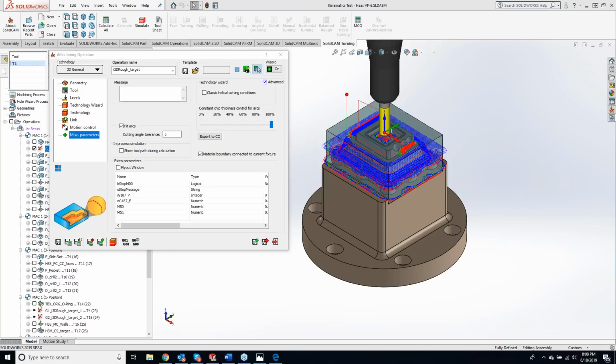It's typically anytime you're switching from a G1 move to an arc move like a G2 or G3, you are flipping an electronic switch there. So by keeping it in the G1, you're bypassing the need for flipping the switches, so you can chew through code. The machine only has to worry about the movement changes as opposed to what type of motion it is. So that's where that would come into play.